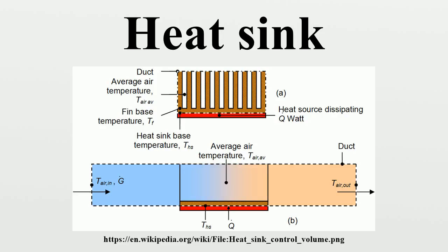Equations 6 and 7 are applicable for straight fins, where h_f is the convection coefficient of the fin: air, 10 to 100; water, 500 to 10,000. k is the thermal conductivity of the fin material: aluminium, 120 to 240. L_f is the fin height, and t_f is the fin thickness. Fin efficiency is increased by decreasing the fin aspect ratio, or by using more conductive material.